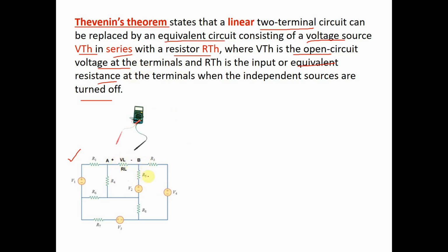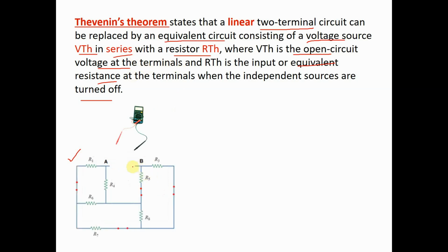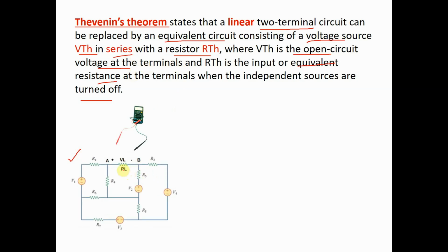Now to obtain the VTH, what we should do is remove the load, RL. So we have to remove this one and try to measure the voltage between A and B. In that case, that will be the open circuit voltage, and that will be our VTH.